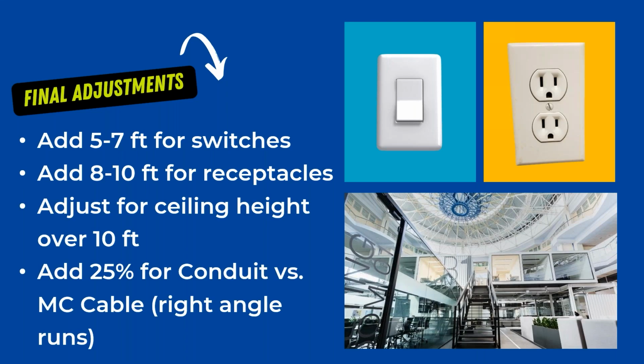And of course, you need to adjust for ceiling height. That's assuming a 10-foot ceiling or less, and you need to adjust accordingly if you've got high ceilings. Now, that average distance between points is assuming you can go straight from one point to another, like you would with MC cable. You just daisy chain everything together.